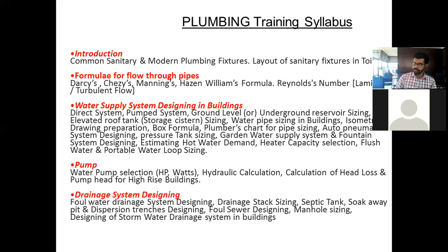Just imagine your house is a single-story building. On the top of your house, you are just keeping it on the terrace. It's not necessary that you will get a sufficient amount of pressure in your fixtures. When you open the tap, it will come very slowly, not in a good pressure. At least you need 2 kg pressure.